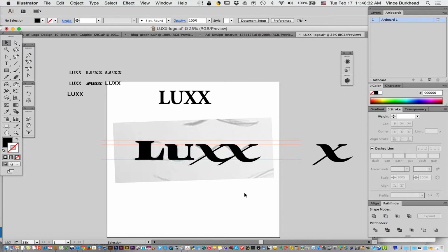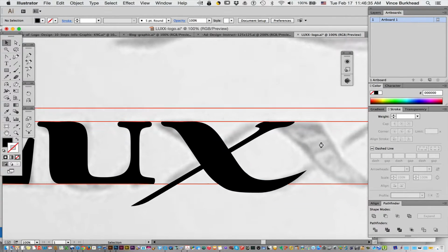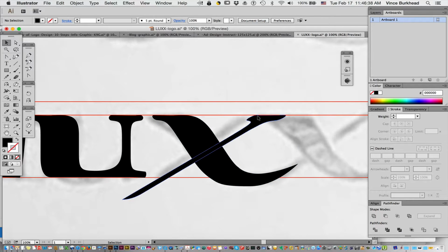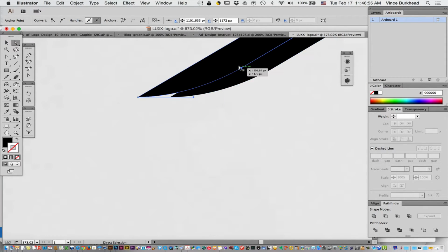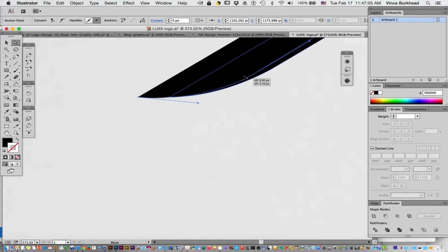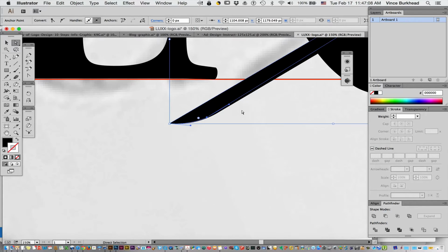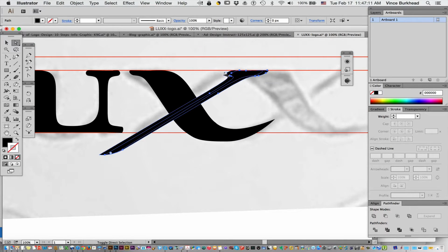I do a lot of zooming in and out because you've got to see how it looks when it's smaller. In order to thicken up that shape, I duplicated it right next to itself, and now I'm going to merge these two. The detail work can really pay off because your eye catches everything. So I can select those two and merge them using the Pathfinder tool. And that shape will hold up better when it's viewed, small or large.